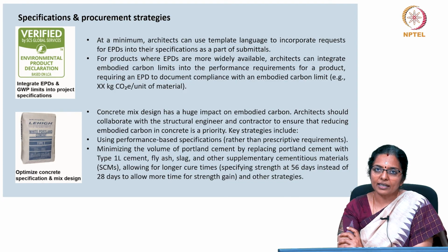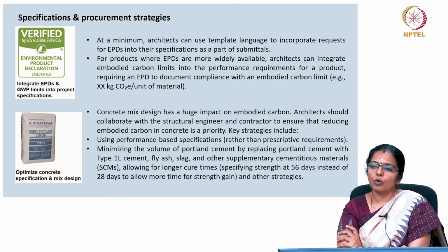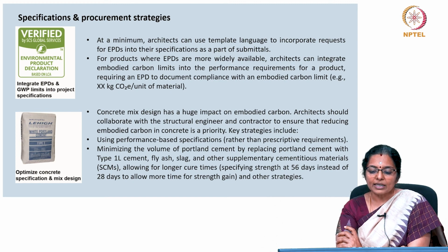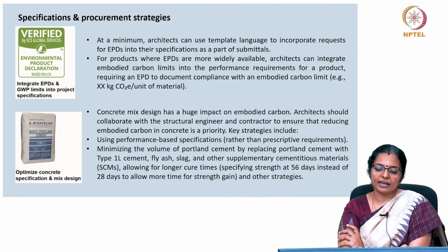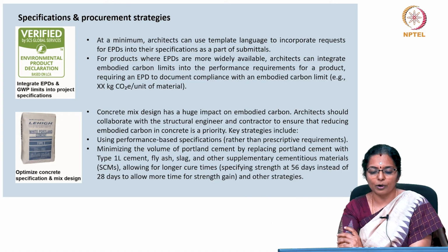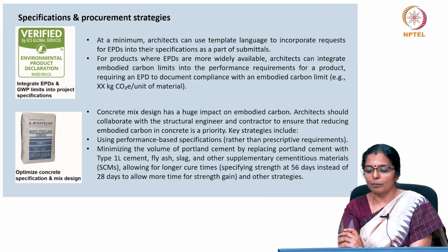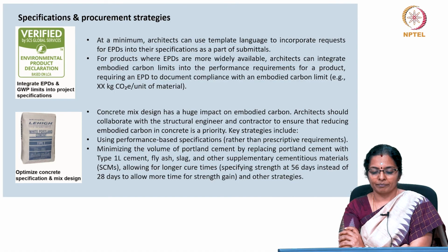Let the architect, the client, the contractor, everybody know what goes into making of the building material in detail. For products where EPDs are more widely available, architects can integrate embodied carbon limits into the performance requirements for a product, requiring an EPD to document compliance with an embodied carbon limit.